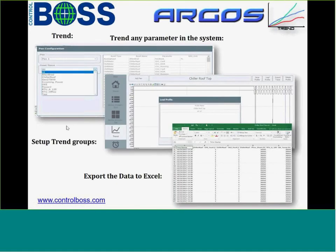The trending system, each time you add an asset, you're able to go in and sort by asset name and then the parameters inside of that asset. We can put up to 15 pins on one trend, and we have the ability to save trend profiles. So I could have a trend for my HVAC power usage. I could have a trend for my OEE production levels, all those type of things inside of the system. And then from that same trend window, you can export that data. We basically take a database dump from the SQL and send it out to Excel in a CSV format. So if you wanted to use it in other systems, you could.